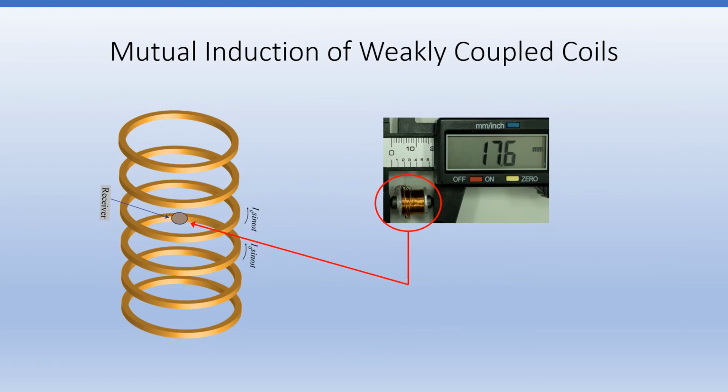Next, the mutual inductance between the transmit and the receive coils was determined as follows. The transmit coil's magnetic field was numerically computed by finite element method over the standard Maxwell equations. The mutual inductance was obtained by evaluating the loop integral of the magnetic vector potential over the receive coil. Finally, the result was experimentally verified.